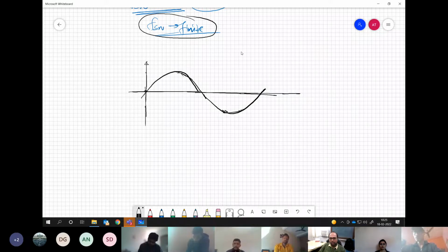Now, in case of a DC-DC converter, we have the ramp going between 0 and 1. Whereas here we want a comparison for a reference signal which has a sinusoidal nature. So maximum values could be between +1 and -1.